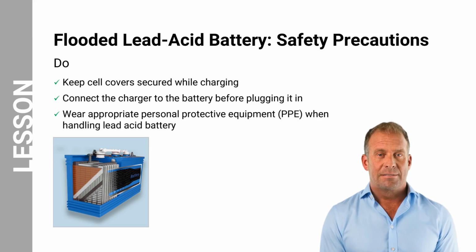Let us now look at the safety precautions for flooded lead-acid batteries. Firstly, let us focus on the do's. Secure the cell covers while charging to prevent sparks and spills. Connect the charger to the battery before plugging it in to minimize sparking risk. Wear appropriate personal protective equipment, abbreviated as PPE, like gloves, face shields, and safety clothing when handling the battery's corrosive acid.